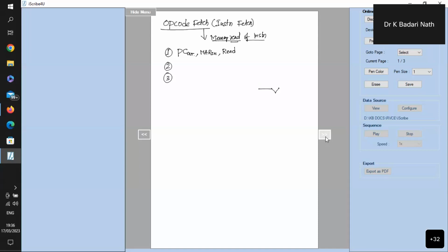I said the ALU is present inside the CPU, which has 2 operands, operand A and operand B. This ALU is also connected to a multiplexer, as we discussed yesterday. The multiplexer is controlled by a select line. One of the inputs for the multiplexer is constant 4. Another input is given from a temporary register called Y. The output of that is connected to the multiplexer, and then this is connected to here. So this Y is connected to the bus.